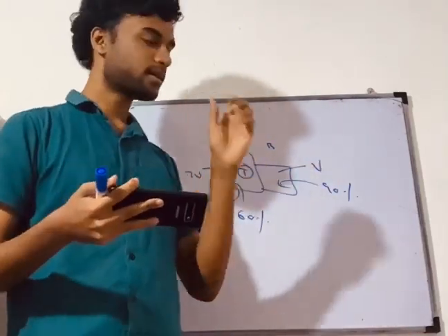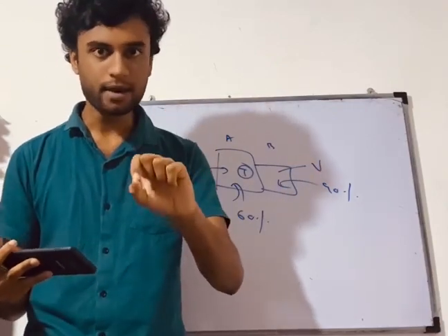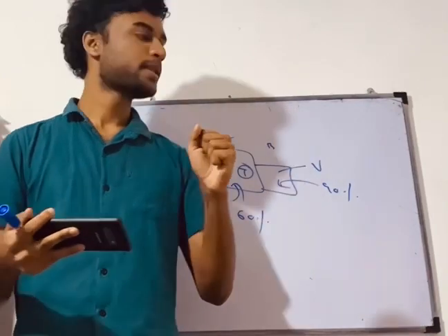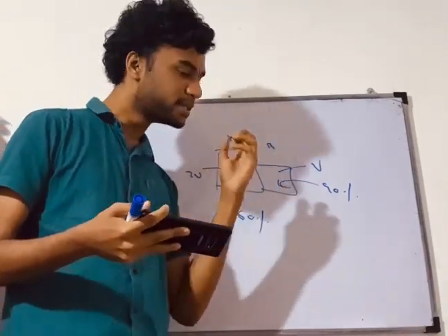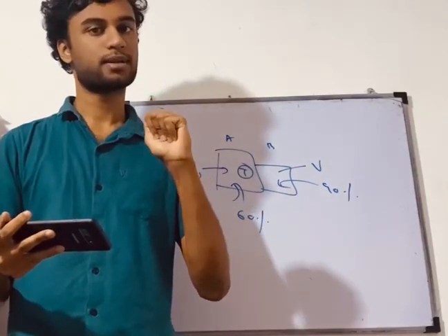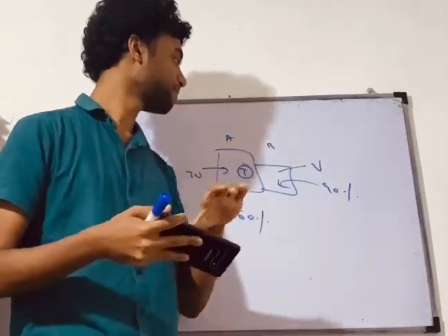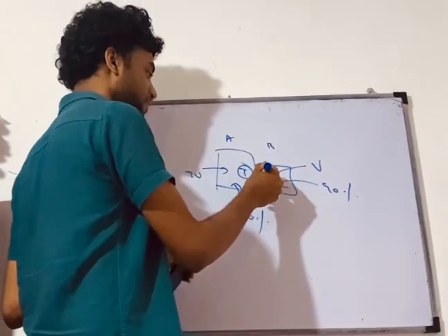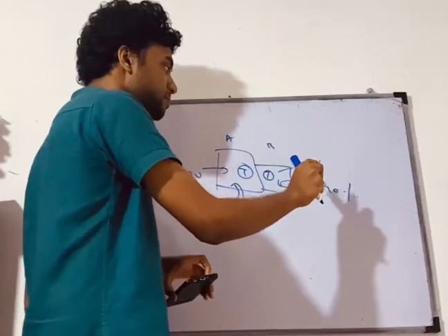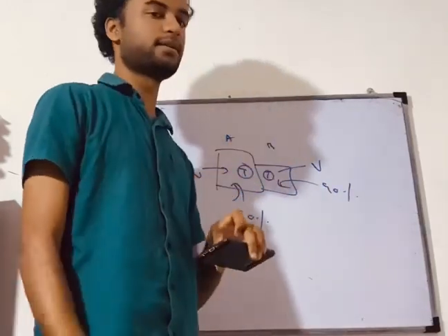Suppose room A and room B are saturated. When you consider the saturated instant, the mass per unit volume, or the absolute humidity at saturation, is going to be the same because the temperatures are the same. Temperatures are the same, but their volumes are different. That means the overall mass in B and the overall mass in A at saturated state is going to be different.